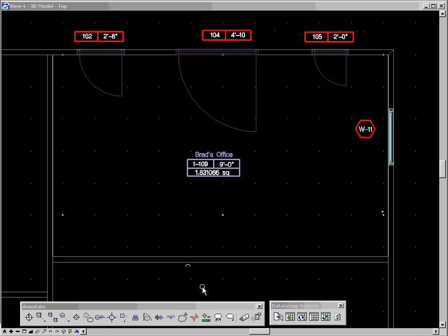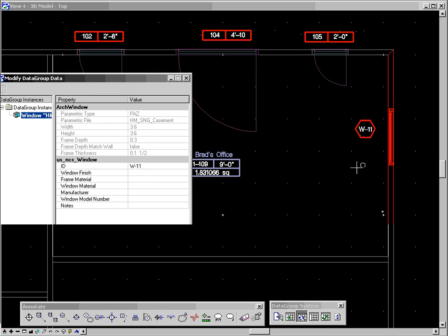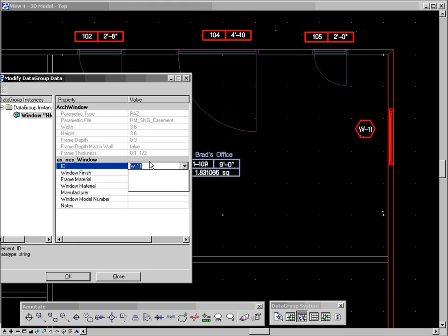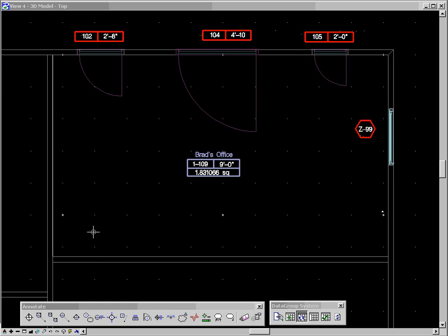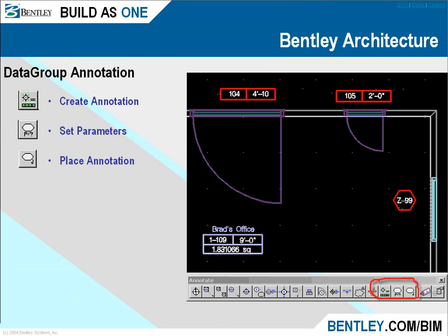Brian? Yes. Is there a setup process for synchronizing the 2D model and the 3D model in architecture, or is it automatic? Yeah, what you do is you apply a seed file that allows this synchronization to take place. There's 4 seed files that are delivered with the product, and based on the workflow that you employ, you just simply merge the file in using a seed file. Once that seed file is applied, the workflow is seamless. And I can show you that later.